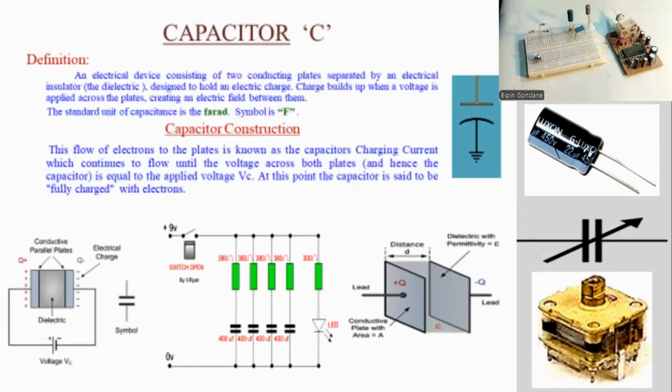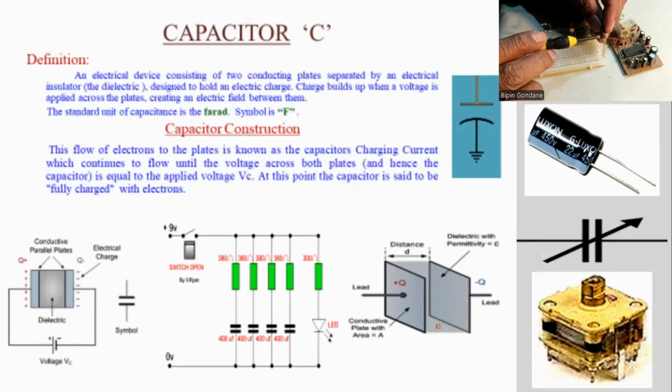Now, again, you can see there are capacitors connected here. Some two of them are in series. This is an electrolytic capacitor. How will you identify an electrolytic capacitor? One leg will be bigger and one leg will be somewhat smaller. And some indication will be there. One side is marked minus. Naturally, the other side will be positive. So the negative side lead will be shorter, and the positive side lead is a little longer.